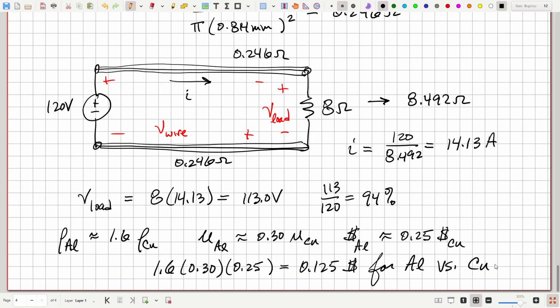And of course, 8 times as much to use copper really is a showstopper in that situation. And you don't care about the larger volume of the aluminum because it's up on transmission lines and it's not having to fit in a box or something or in your walls. And aluminum's not quite as pliable as copper, but you don't really care about that for the transmission lines, but you would for household wiring.